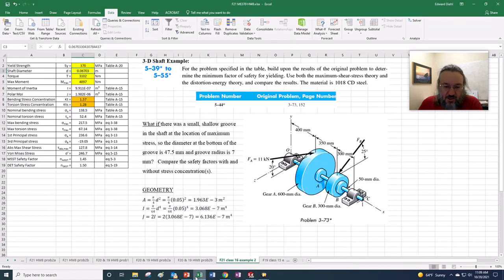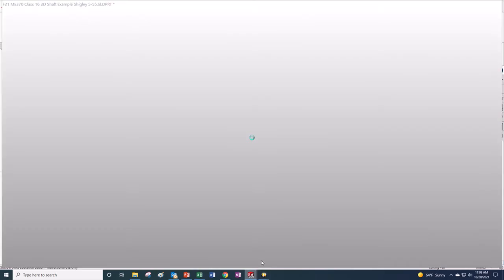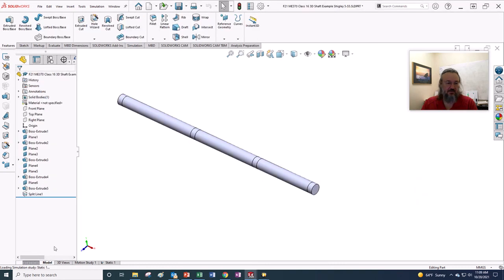And we could do all this. Let's try this out. Let's set these to 1, and let's pick this as 0.07 right there. So we're going to predict that our maximum von Mises is 145.7 if we have a 7. And notably, we got rid of the stress concentrations, so it's going to be greatly reduced. So if we have 70 millimeters without stress concentration, I'm going to predict 145.5. And I'm going to use this guy right here.